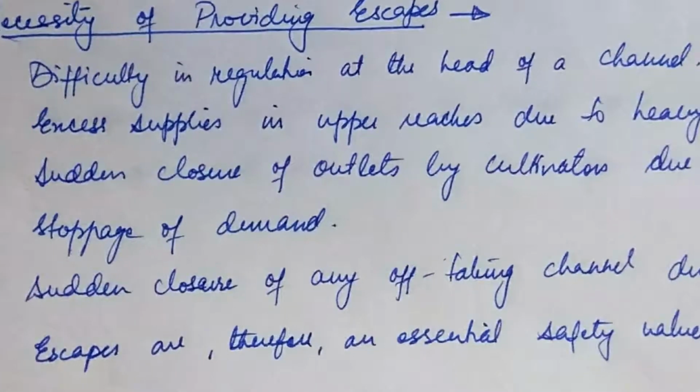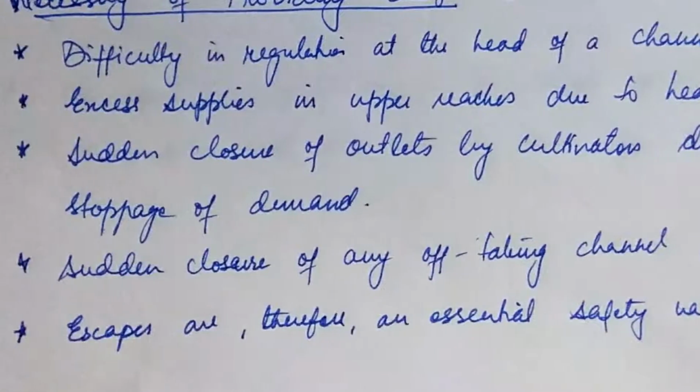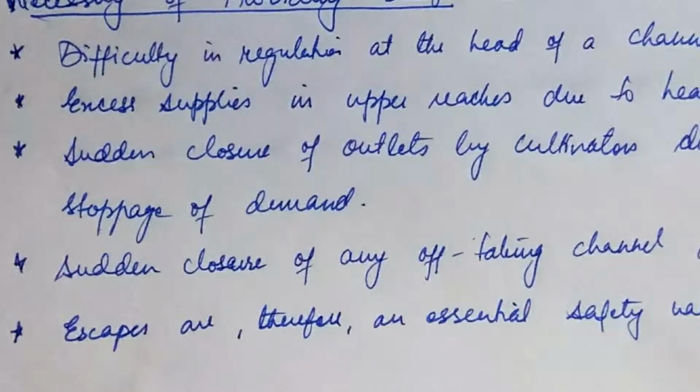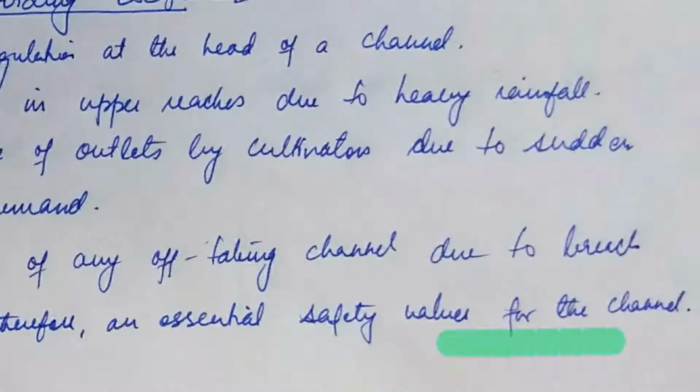Then sometimes there is sudden closure of outlets by the cultivators because of a sudden dip or stoppage in demand. Then there is sudden closure of any off-taking channel. To take care of that discharge, we need canal scapes to let go of the excess water. And scapes are therefore essential safety valves for the channel.